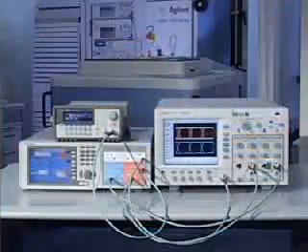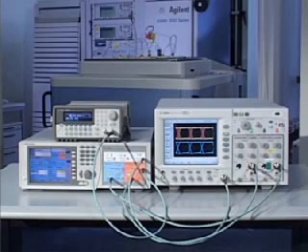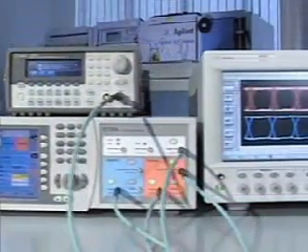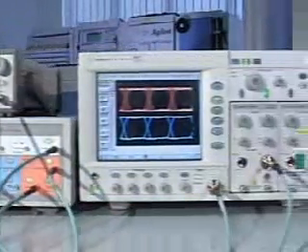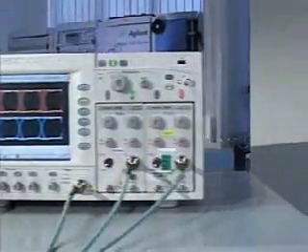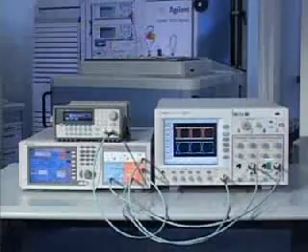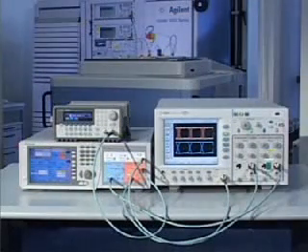We're using an Agilent 33250A arbitrary waveform generator as modulation source. It is simply connected to the delay control input. The delay control input sensitivity is selected, which also controls the maximum values of jitter to be added. The 81134A adds a specific amount of delay to the output according to the voltage that is attached to the delay control input.